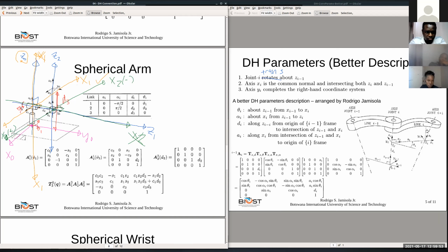Now going to the end effector frame, we already mentioned, just for convenience, you can put it somewhere, just follow the orientation of the last n-1 frame. So frame 2 is this, and frame 3 can be the same orientation. There, that's frame 3. Just put it there where the hand is. I think the real picture is like this. This one is long like that.